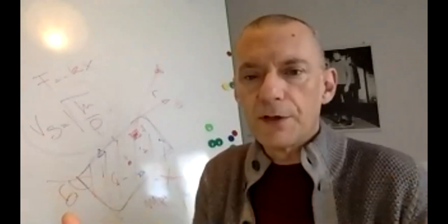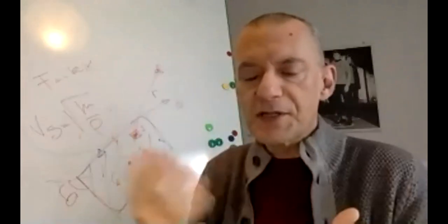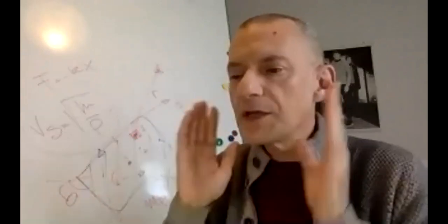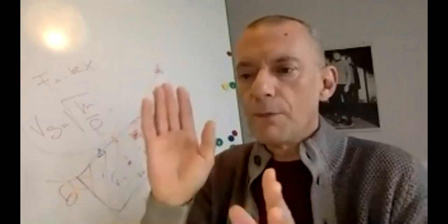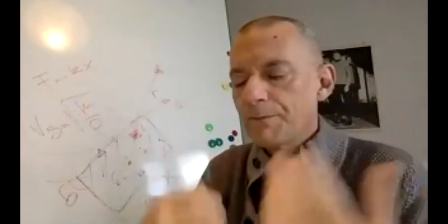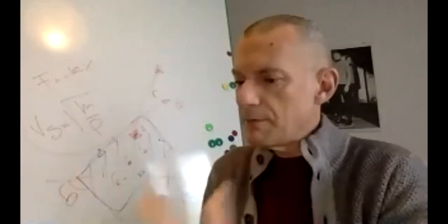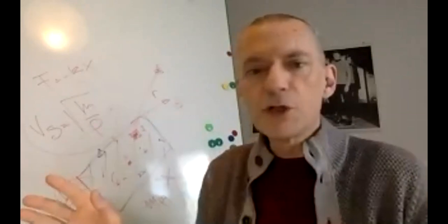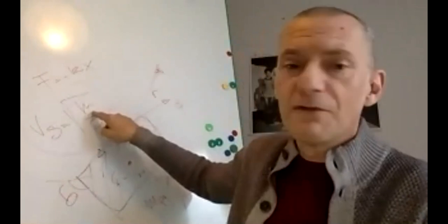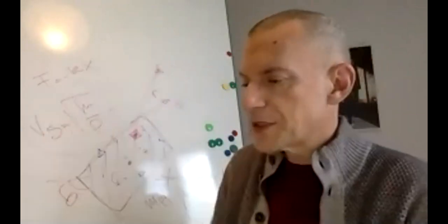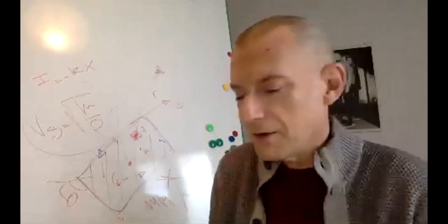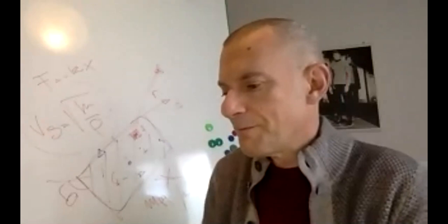There is no time there. There is no time for the system either to relax or to unrelax. Everything is immediate, takes no time. You apply force, you get a displacement, or stress and strain, and vice versa. And when you remove the stress, immediately the system goes back to the initial condition. That's Hooke. There is no time there. And you can imagine that mu, the ratio between stress and strain, is a real value, as it should be. It has its units, whatever.